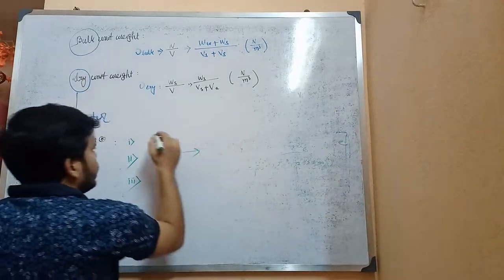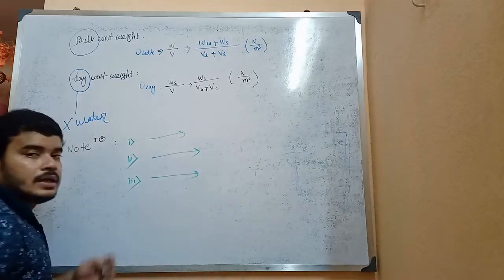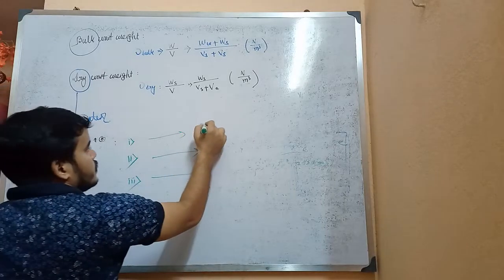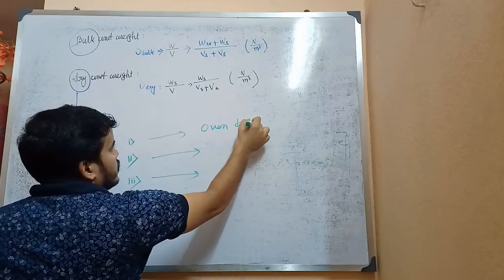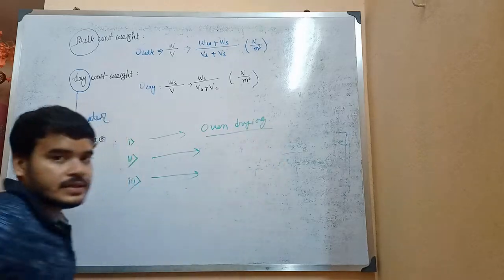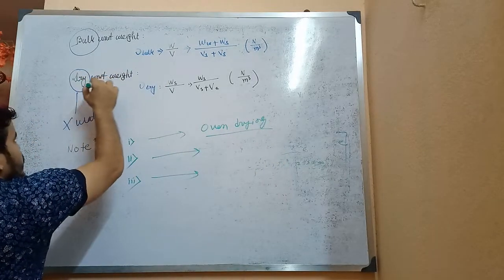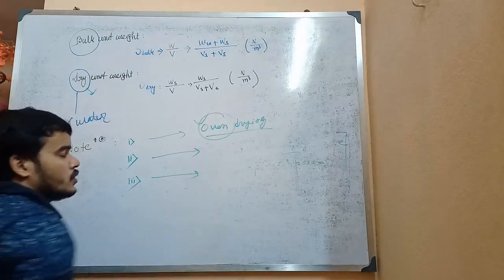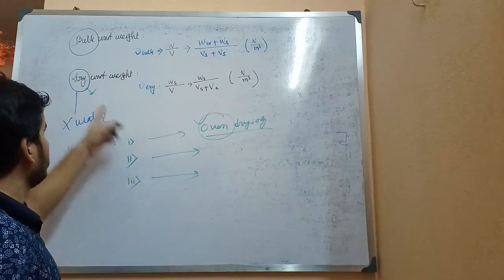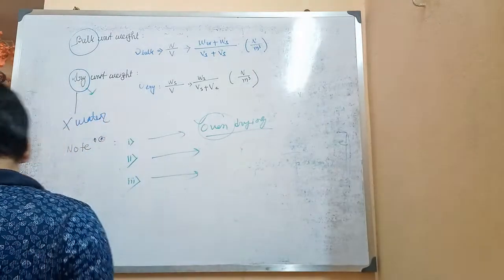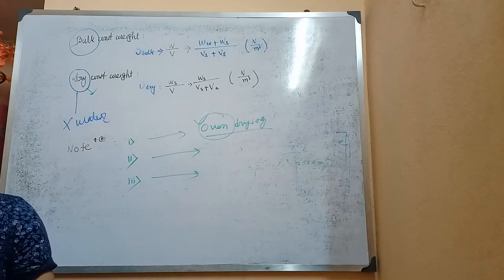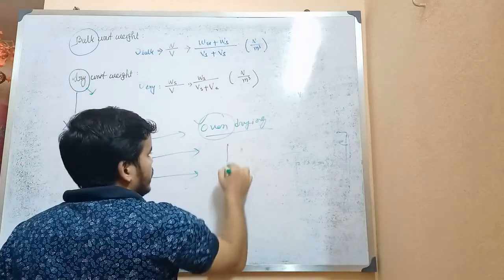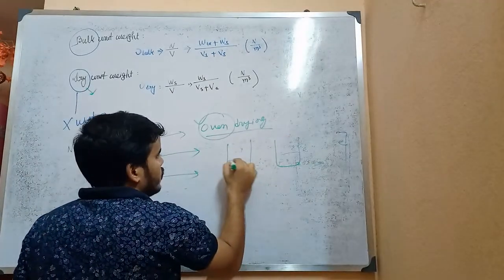So now we will understand these three terms. In the first term, what we have learned, gamma dry should be taken after oven drying. That's a very basic thing. If we have to make the soil dry, we have to put the soil in an oven to evaporate the water, so that after that we can get the dry unit weight. And second, dry unit weight of soil is an indicator of denseness of soil, as dry unit weight only deals with the solid particle.